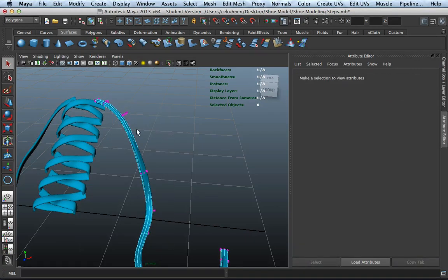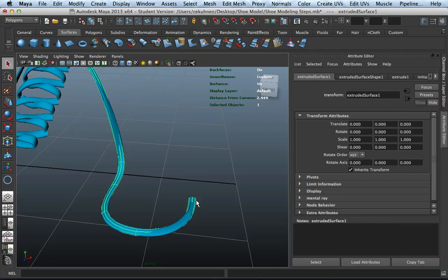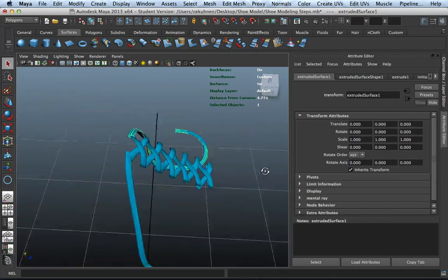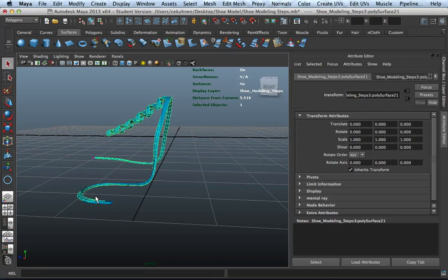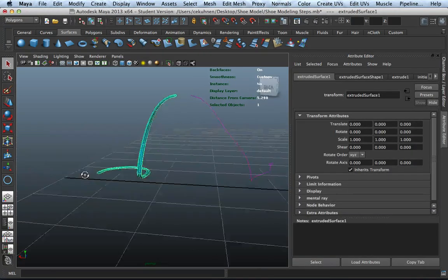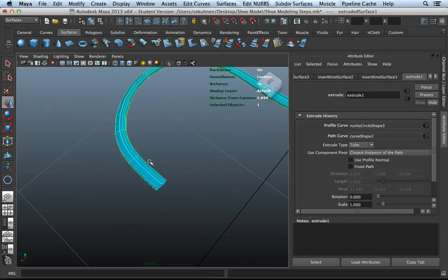Then let's go to object mode. And what object do we have? That's a poly surface. I would like to have my NURBS surface. Okay, so you see, we basically blocked out most of our NURBS model. So at this point, the NURBS surface, we, for example, can convert into a polygon surface, because like here, the end needs to have a different design, so it's very blocky.